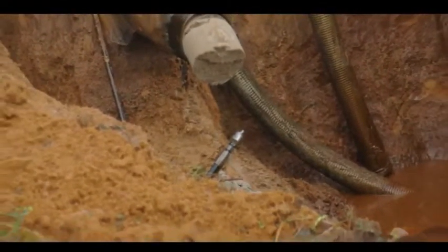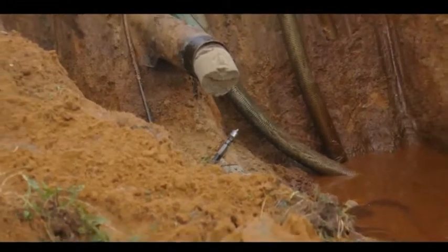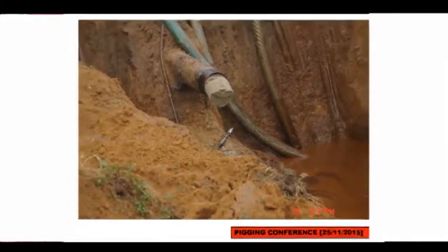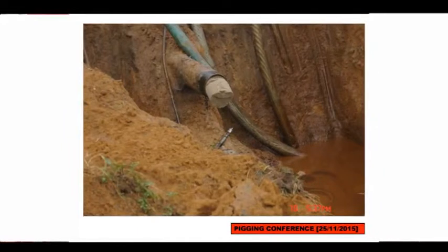Gentlemen and ladies, this is a pipeline, I think 8 inches. It belongs to one of the operators in Nigeria. It had been run for quite, I think, more than 20 years, no problems. One day, the guys responsible for pigging set out to go and pig the line. They launched the pig, and they were expecting that after 45 minutes, they would have recovered this pig. 20 minutes down the line, the pipeline blocked. There was no movement. With devices, which we are going to talk about later, they located around where the pig was and cut the line.